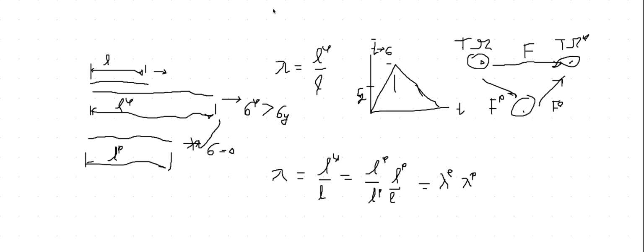So this is the first part of the idea that I want to explain. And that is really corresponding here to the total deformation gradient. These are the results introduced by Lee and Mandel, that this is a product between FE and FP. These are now tensors, so this is a product of these two tensors, and these are just scalars because it's the 1D case.